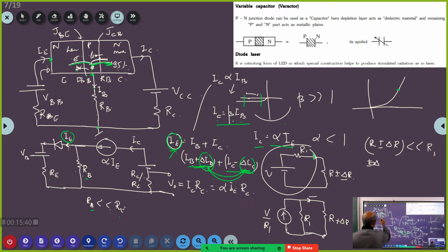Will this voltage increase or decrease? This is VD; here VD becomes VBE, and this becomes IB. It is IB versus VBE. Initially the operating point was here, for some VBE there was this IB. Now, if VBE decreases or increases, there is a corresponding change in IB. Agreed?